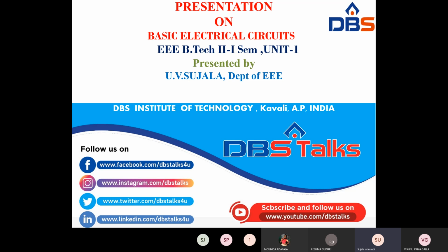Assume the polarity according to the direction of the current, with a rise of potential as positive sign and a drop of potential as negative sign. The total equation will be that the algebraic sum of the voltages is equal to 0. This is about Kirchhoff's voltage law.